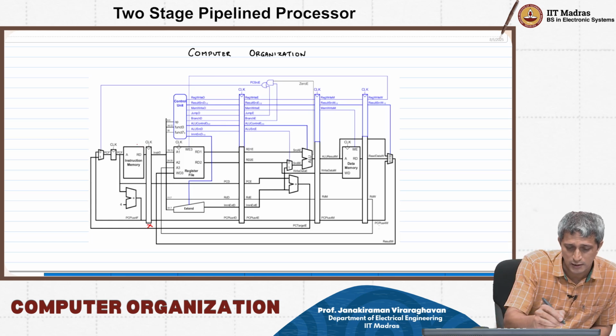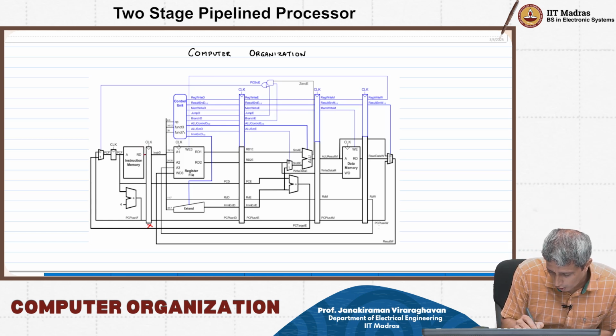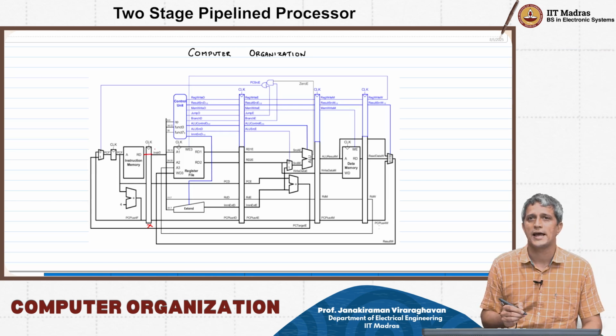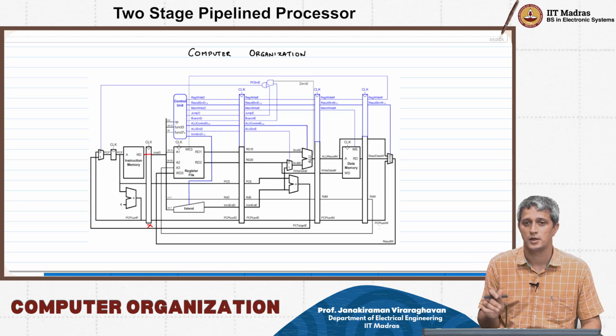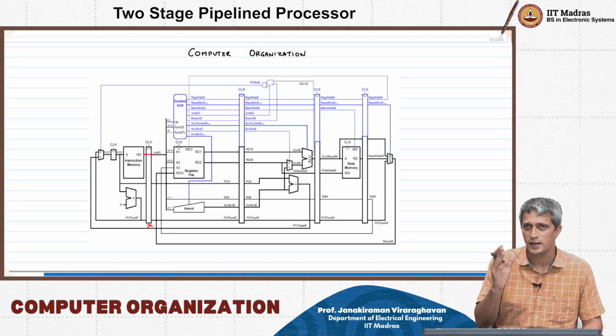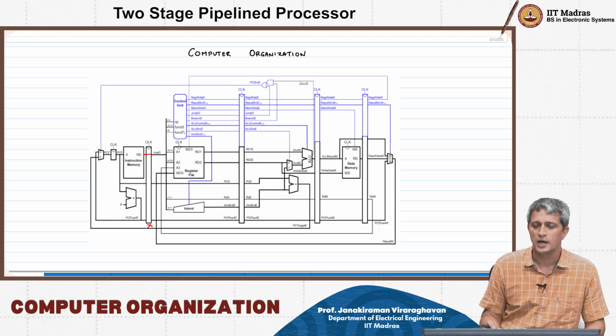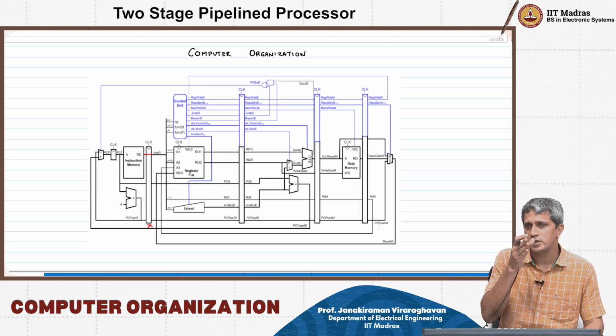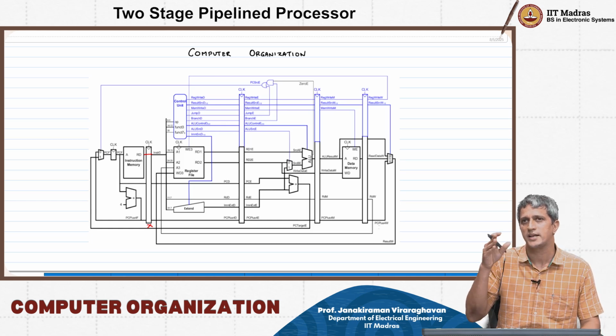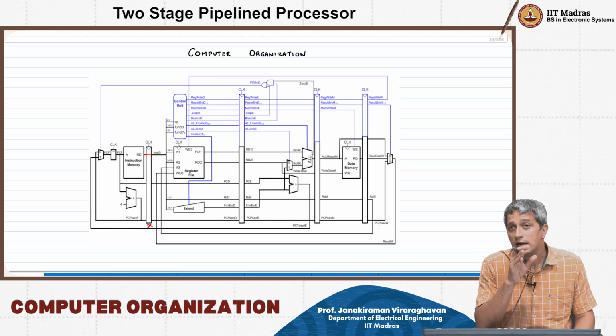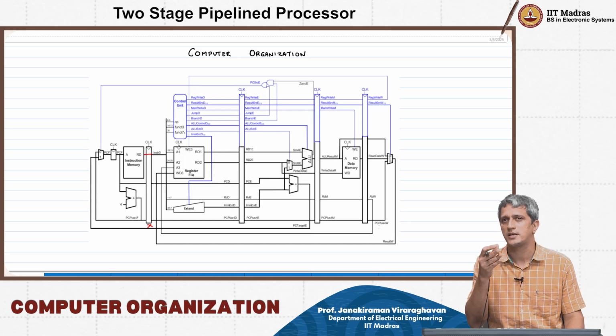It basically says that the signal from the instruction memory can flow in directly to the register file and decoder controller, right? Earlier, the output of the instruction memory, the read from the read port, was basically called INSTR. We now added the flip-flop and therefore called it INSTR-D.